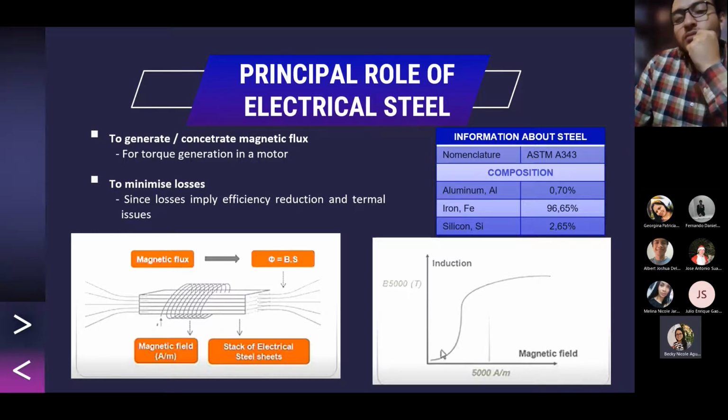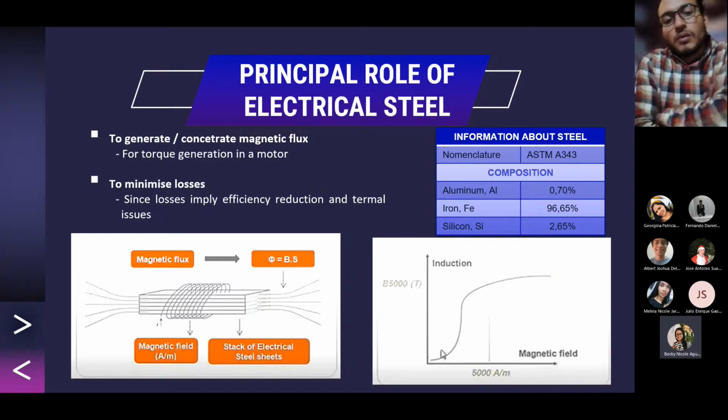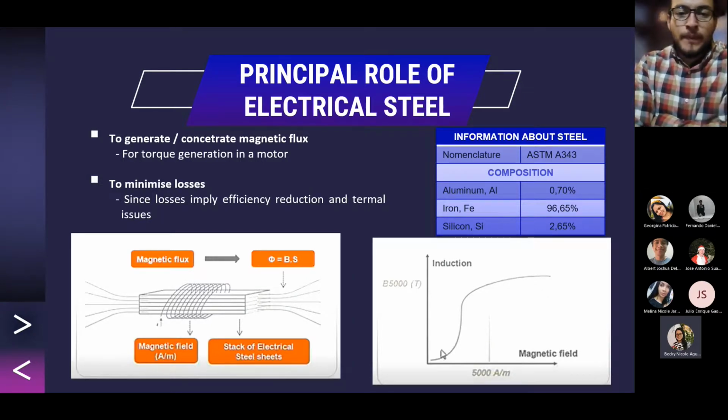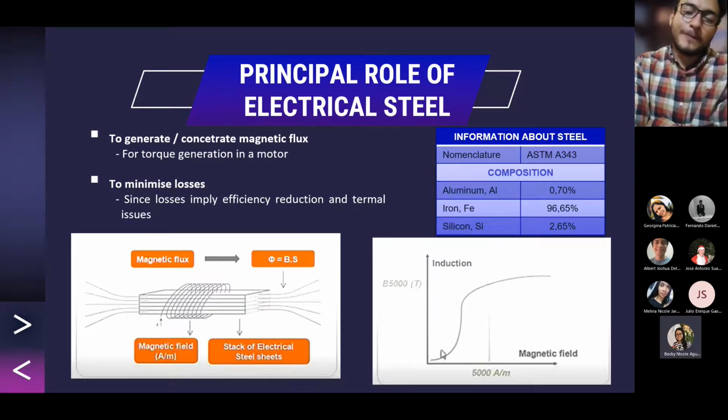The interior of the steel is changing in terms of magnetic structure, and this will lead to loss within the steel. That is why the motor heats up when it works. Inside the steel there are irreversible processes that generate heat that is not effective for the mechanical power output. So it is required to have electrical steel that has good flux generation and does this with minimal loss.